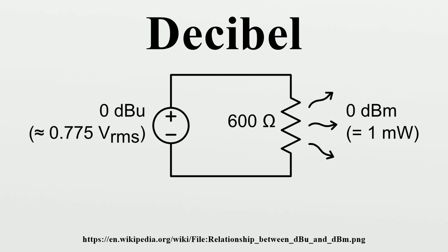In order to find a representative value of the sound level in a room, a number of measurements are taken at different positions within the room, and an average value is calculated. Compare the logarithmic and arithmetic averages of 70 decibels and 90 decibels. Logarithmic average equals 87 decibels. Arithmetic average equals 80 decibels.